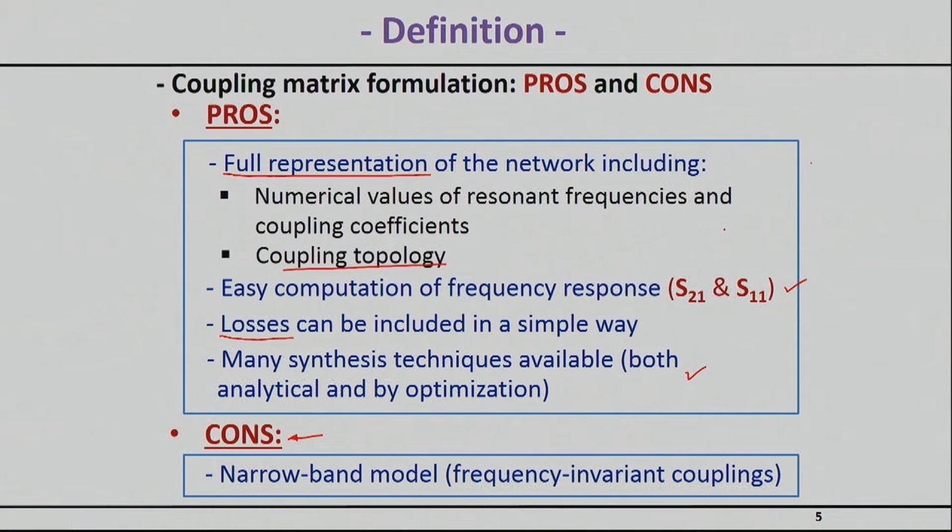So when you see a matrix, for example here, and you have to hit a coupling section of 0.52, it basically means you'll hit that at only one frequency because your inverters will change. So you need to be very careful that the coupling matrix will give you a good response close to resonance, so you will get something like this, but away from resonance, it's likely you will see things that the coupling matrix will not predict for you.